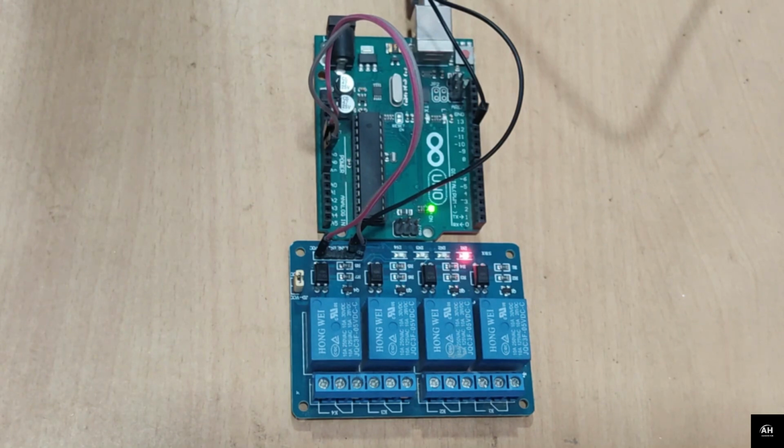So basically we're going to be building that in this video, so it will automatically turn on the table fan for us without our input by just getting the temperature from the room with the help of a DHT11 temperature sensor, and it will try to sense the environment, and according to the temperature it will control the table fan for us, and it will automatically turn on the table fan as soon as the temperature rises above the threshold value that we have set in our code.